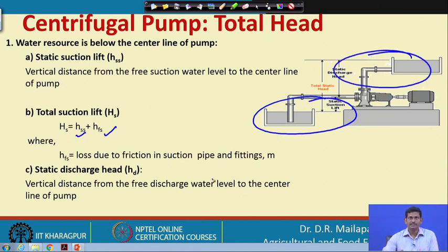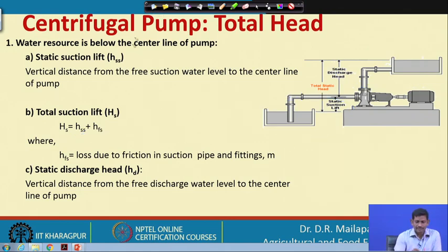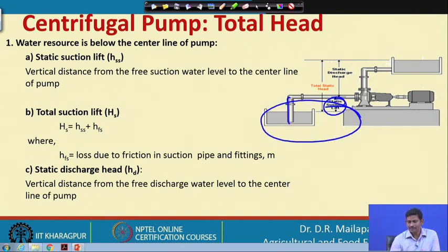In both cases we are going to estimate the head losses individually. For the suction case, we have the suction lift and the friction head losses present in the suction pipe. In addition, we have to consider the bends present in it, and also the velocity head.